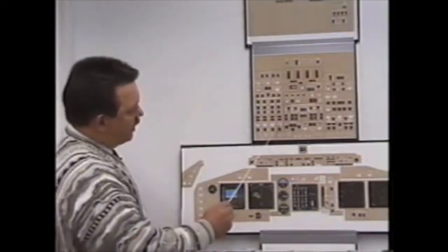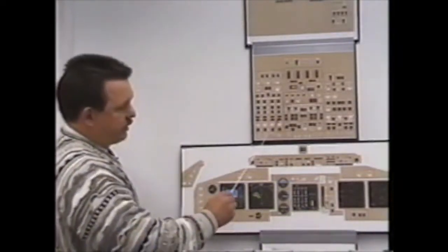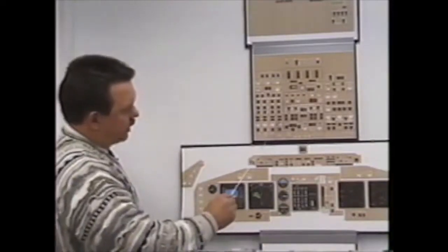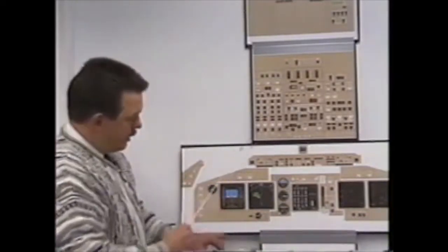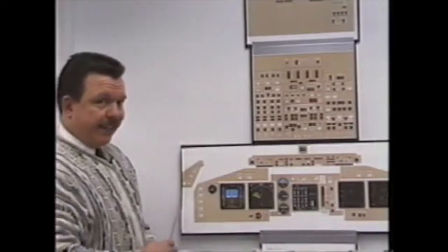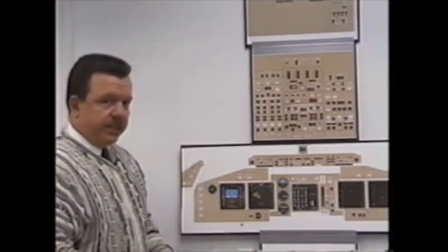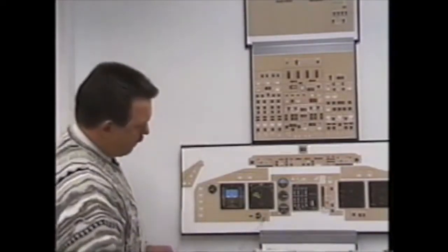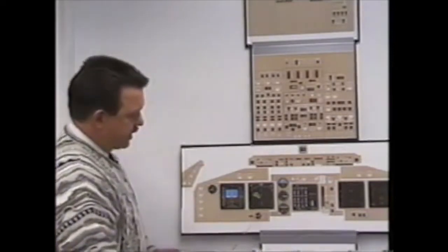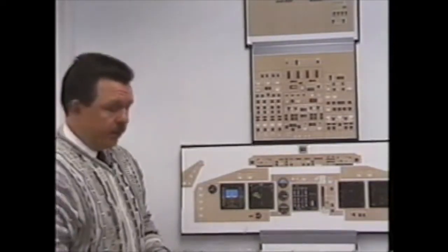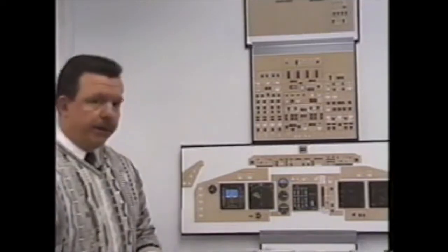Now if I was to then reach up and kill System 4, I lose system pressure in 4, the brakes should go to alternate System 1. But my brake source light illuminates, indicating that change did not occur. So as a result, my brakes are right here on the accumulator, which is not going to stop the plane. The accumulator is designed to set and hold the parking brake only.